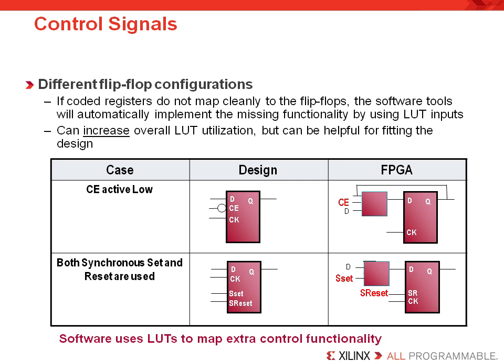As I mentioned earlier, your synthesis tool can map clock enable and synchronous set or reset functionality to a LUT input. This is very powerful for being able to group registers into the same slice since all the flip-flops share the same control signals. In this example, we see how a clock enable and a synchronous set or reset is mapped to a LUT input.